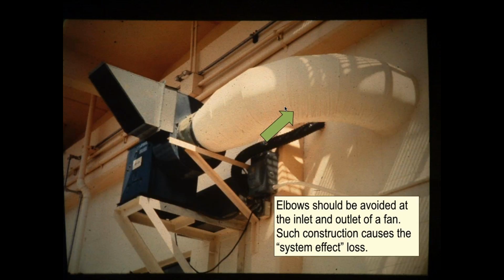So if that's all the length you had, therefore you should... Yeah, you absolutely do not want to do this. Put a turn right at the fan. Right, because that really increases the inefficiency. So you should reduce the duct. No, you should. If you got to make a turn, you should go in straight.